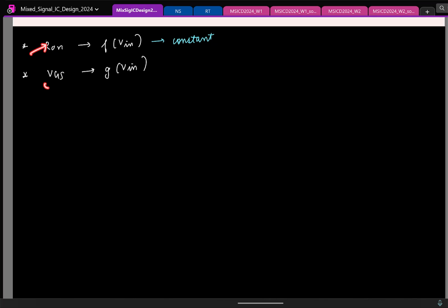To address the effect, you go and address the cause. That is one of problem solving. So you fix this and try to make this constant. And let us say we are looking at an NMOS switch. You want the VGS to be constant. So you want to have a small value for VGS or a large value for VGS? To turn the switch on, you want a larger VGS or a smaller VGS? As large as possible. So the constant large value, what do you choose it to be? The supply we have, the maximum you can.